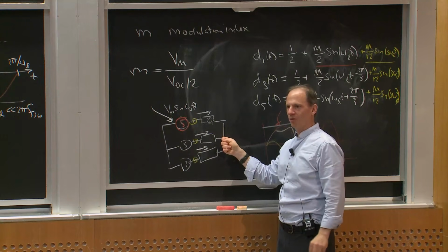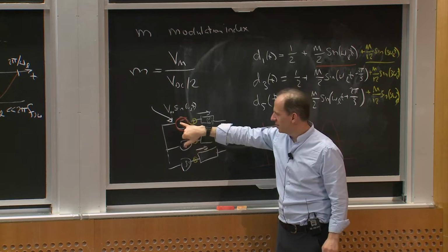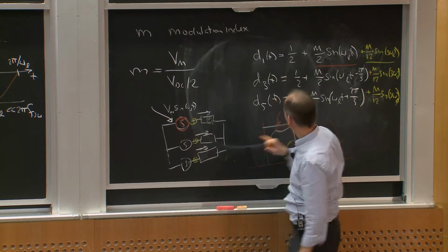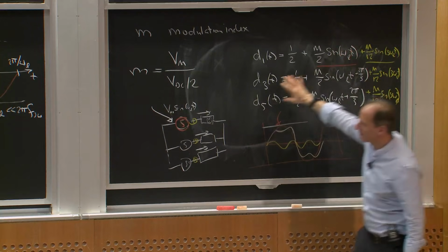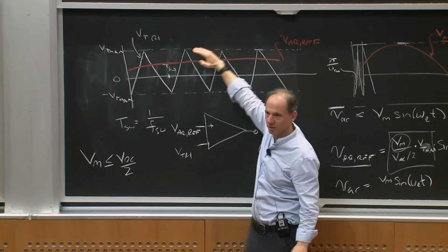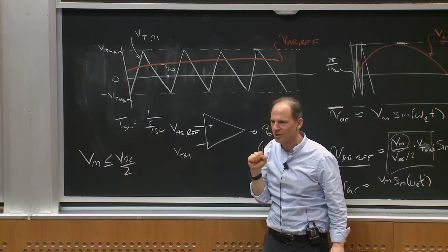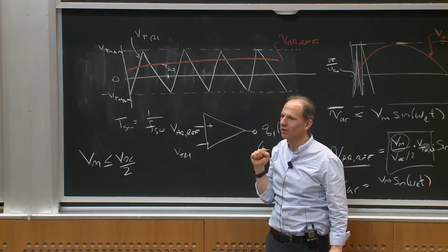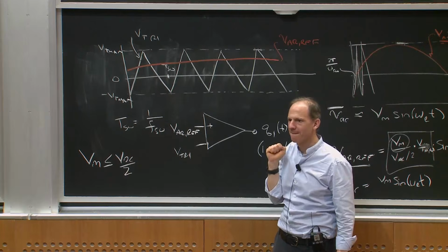They just show up at the neutral, and the neutral goes up and down by the third harmonic. So I can keep this component pure because I'm not saturating my comparison anymore. I'm not making this signal go out of range for that extra roughly 15% of modulation index over 1. So I can go up to M of 1.15. Does that make sense?